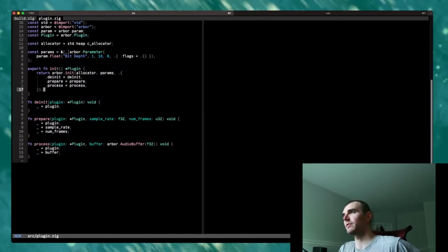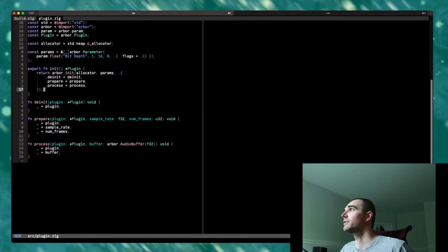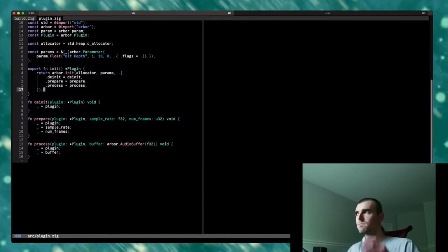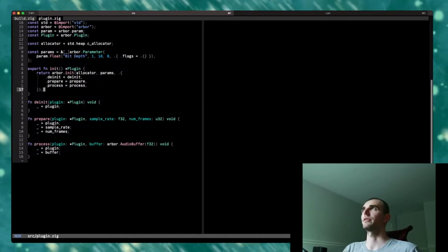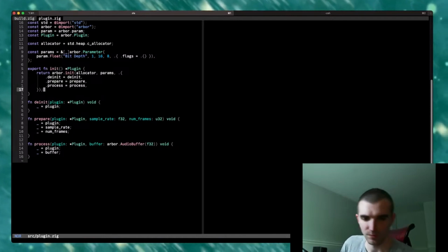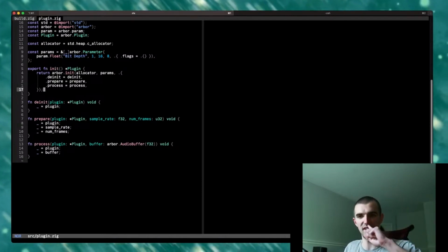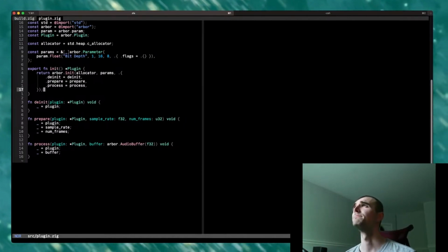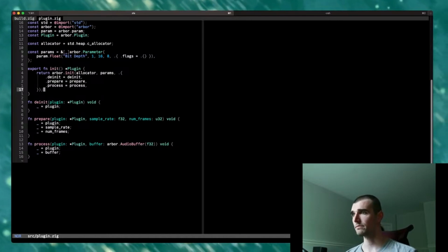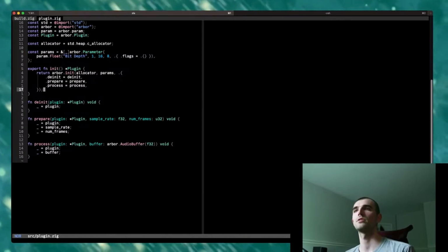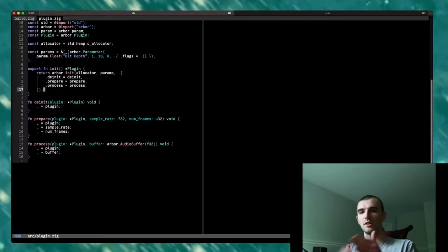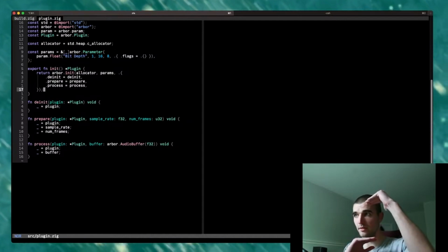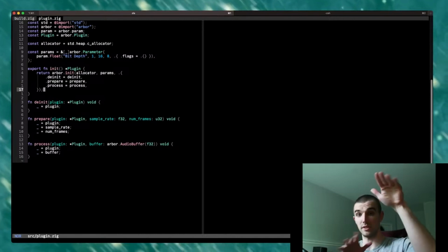So now you want to think about how this is going to be implemented in processing audio. If you're going from a floating point range, we have either 1 or -1, and everything in between is some kind of decimal less than 1 and greater than -1. You can see those numbers as fractions, or as a percentage of the maximum possible amplitude of an integer representation of audio.